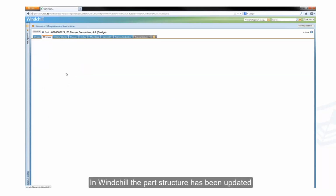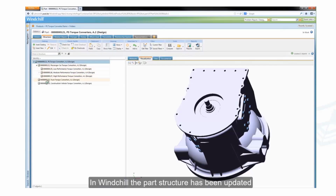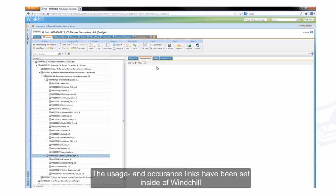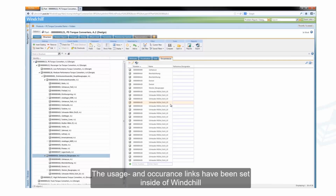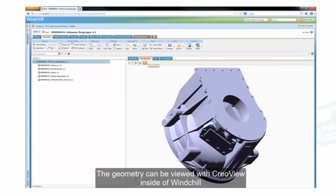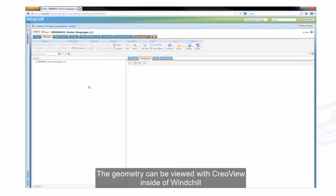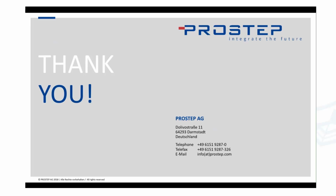So now within Windchill, if we go to the structure, it's more complete, including the other subassemblies here, as well as generating the Creo View data. So you can take a look and drill down through there and see that the Creo View is available for these new structures. So we can go see that there's usage and occurrence links, make sure that it's all set properly, and see the attributes and other types of information for it, as well as visualization. We can set all sorts of data here, so lifecycle templates and status and other types of Windchill data as well.